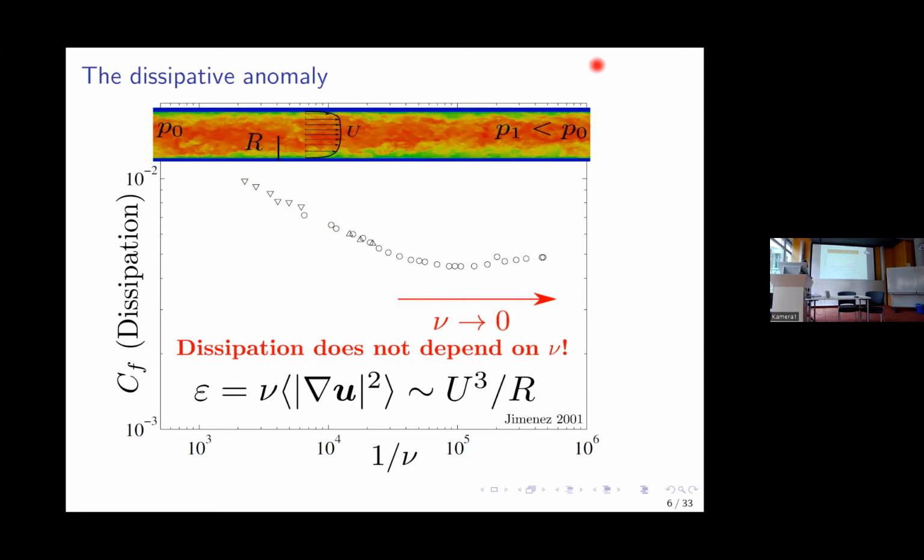And the idea is that you don't want to waste a lot of energy moving the flow, because you just want to move it and you don't want to spend energy. Energy is money, and that's something that people are concerned about, which is normal, of course. And so you know that the dissipation has to do with kinematic viscosity, with the gradients, and you want to try to control this flow. So the first thing that you try to do as an engineer is try to reduce the kinematic viscosity, because it makes sense. It's something completely normal. Maybe if this is a liquid, you can change the temperature to make sure that the kinematic viscosity goes down, and you try to see what happens.